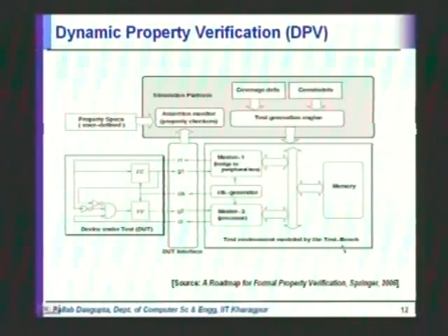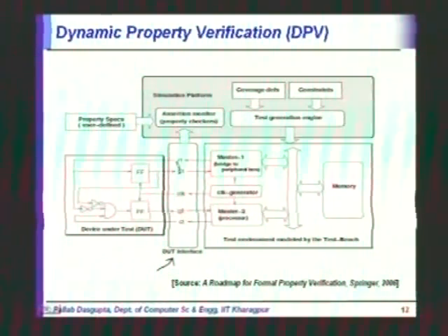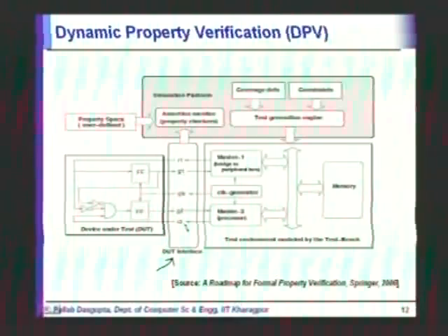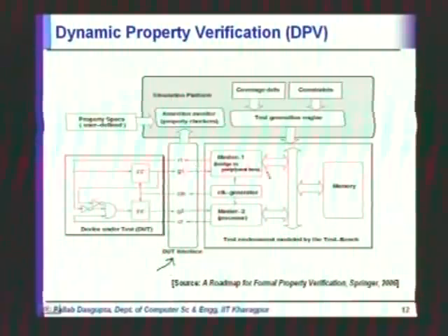Okay. Now in these modern languages we have the concept of an interface, which is one of the new things that came up when we had SystemVerilog developed out of Verilog. What this interface does is that you can define that these are the variables in the interface, and you can bind the interface to this side as well as this side.